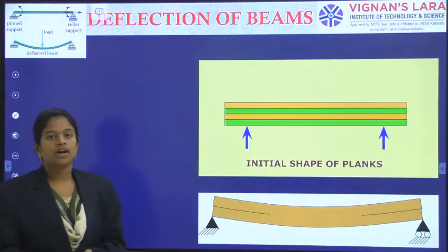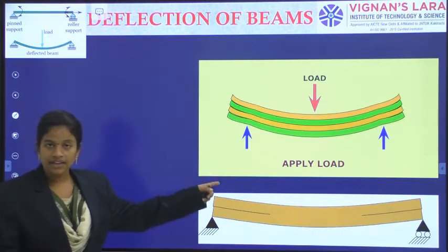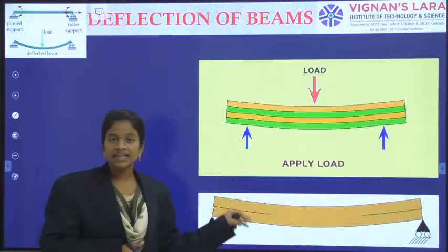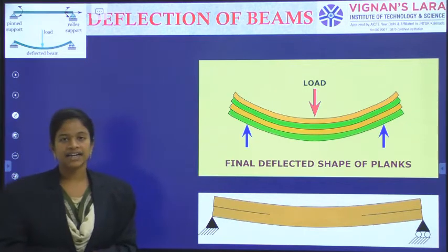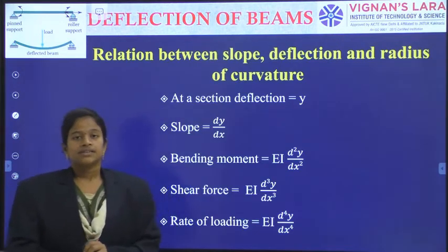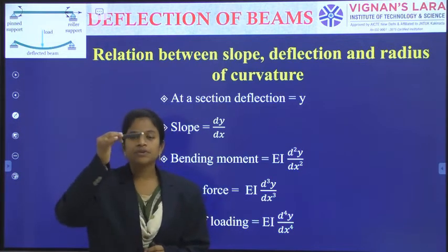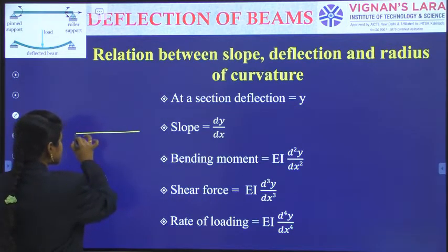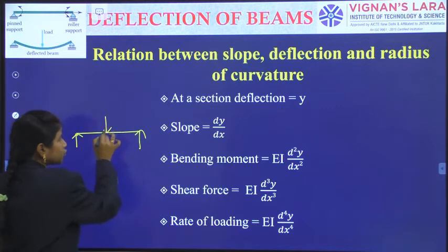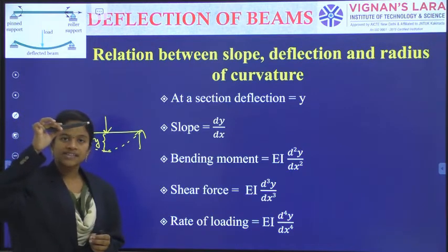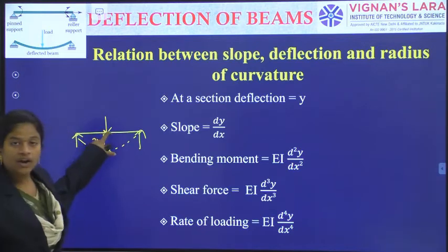Firstly, the first word they have mentioned is this. So, as I am applying the load, we have already indicated it is bending into a circular arc. The bending is occurring into some segment or circular arc-like structure. And then, generally, deflection of a beam, deflection means displacement from the original position. So, originally, the beam was like this. Okay, but due to the application of this load, it has taken some new shape. But this point has reached this level. So, the vertical displacement of the horizontal line to make the curve, this portion we call deflection.